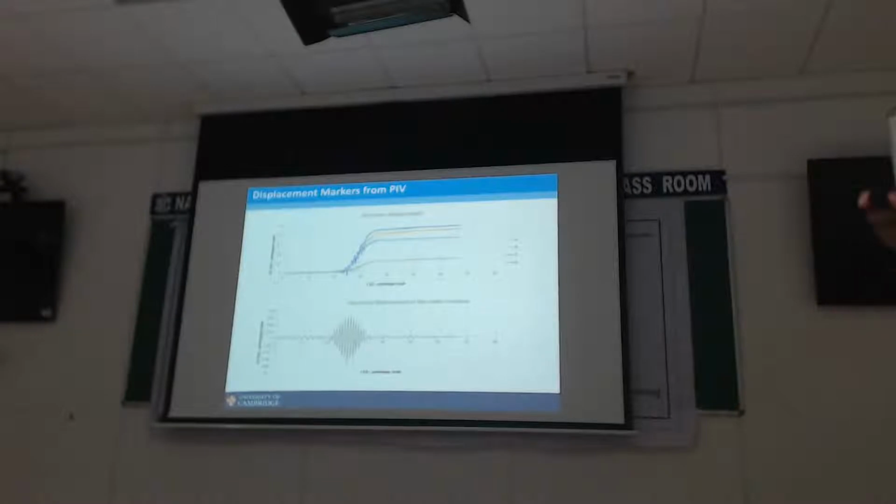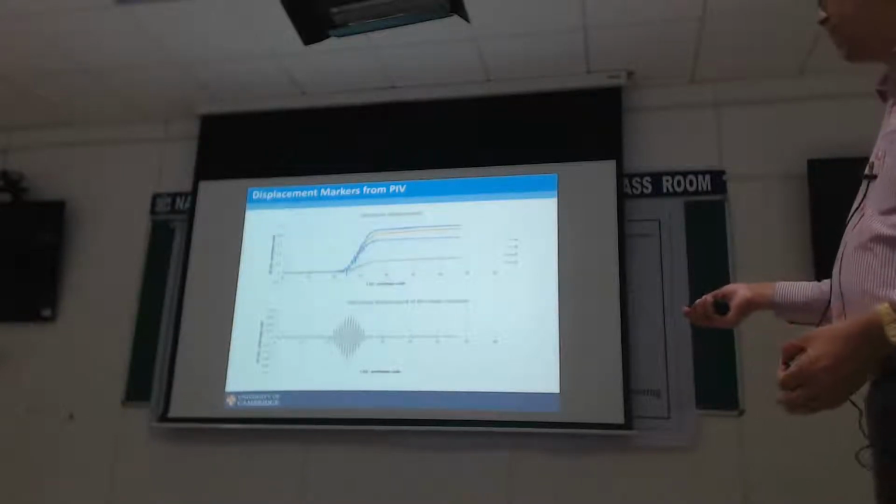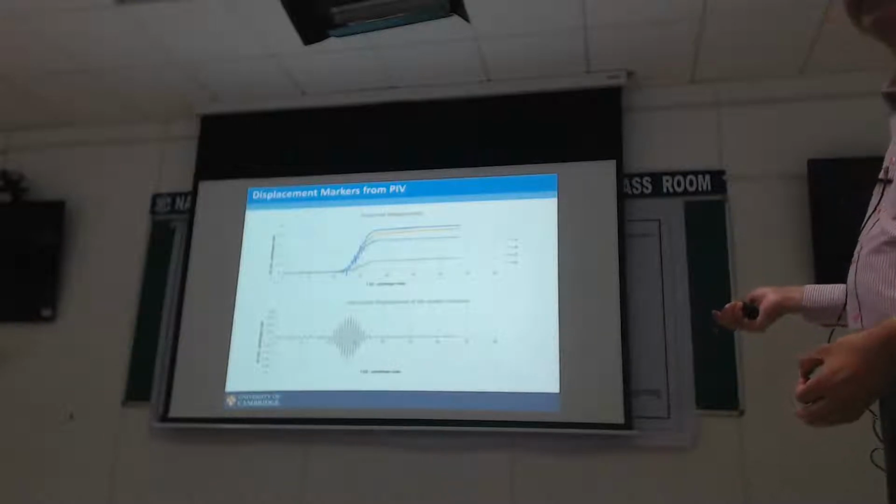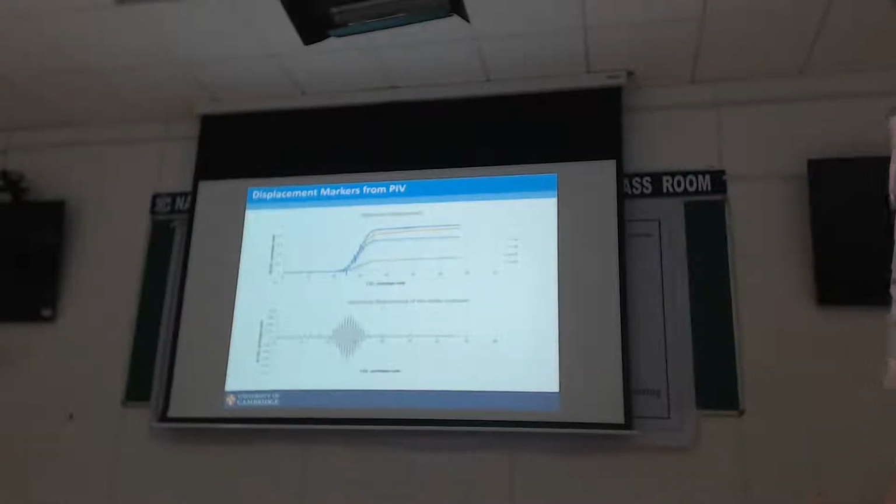Also, because we can track the dots on my box, I can get the displacement of the whole box. How much is it moving by? And that confirms that the motion we imparted is exactly what we wanted. So you don't need displacements. The input motion we measure acceleration, but we can also get the displacement of the base directly without integrating.